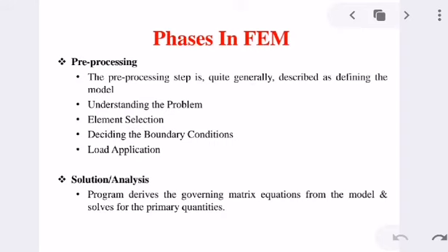The computed values are then used by back substitution to compute additional derived variables such as reaction forces, elemental stresses, etc. As it is not uncommon for a finite element model to be represented by tens or thousands of equations, special solution techniques are used to reduce data storage requirements. For example, for static linear problems, a wavefront solver based on Gauss elimination is commonly used. Just for example, I mentioned it.